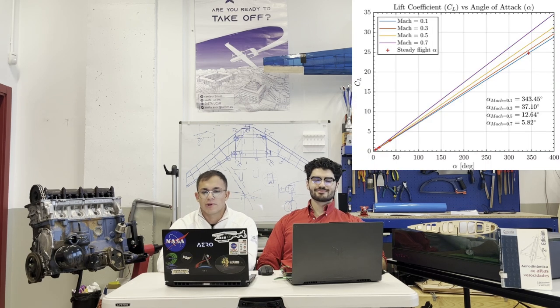First, the CL alpha increases noticeably as we increase the Mach number. However, it should be noted that level flight cannot be attained for Mach numbers lower than 0.5, because the angle of attack needed will be far too high, and as it is a linear increment, it is not physically possible. In consequence, the model does not consider stall nonlinearities and will yield unfeasible values. In reality, this is not an issue at all, because those lower Mach numbers correspond to certain phases of the mission where the plane is neither steady nor level. For example, climb, descent, takeoff, or landing.